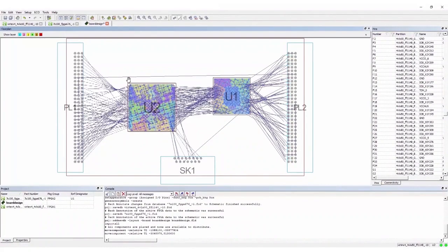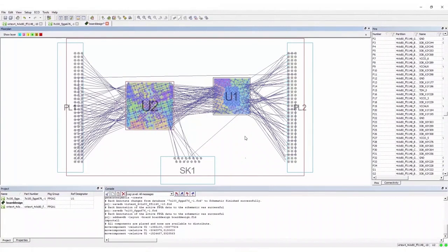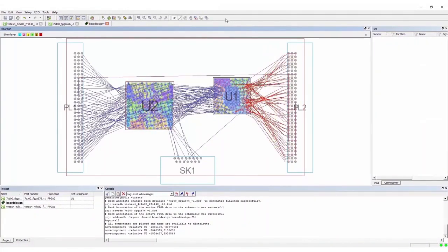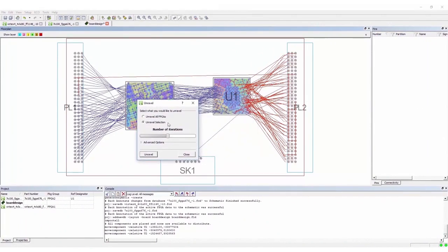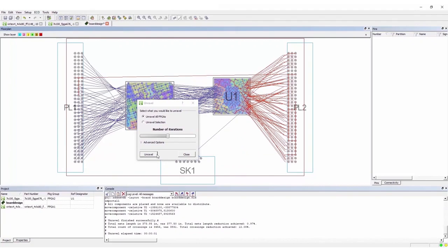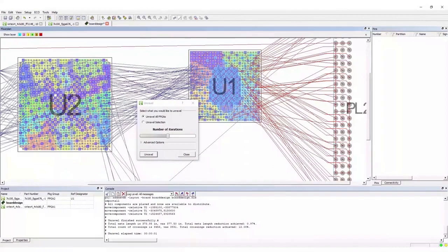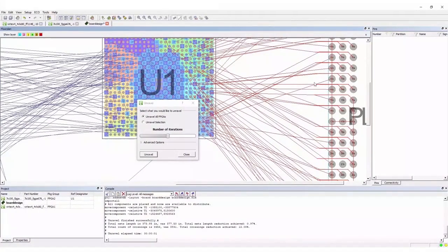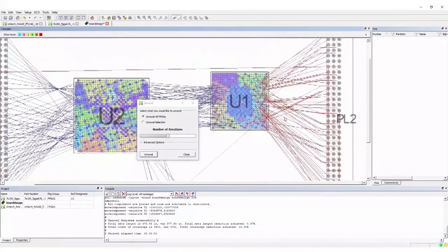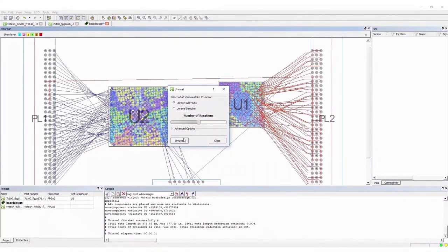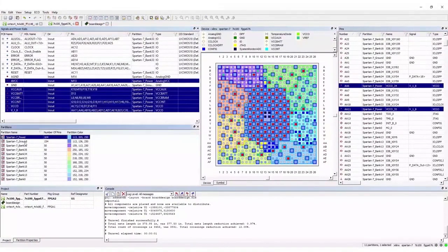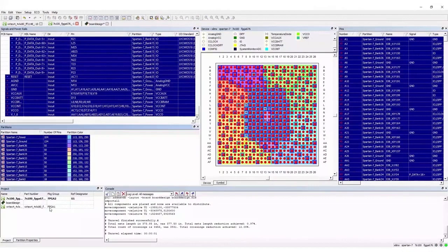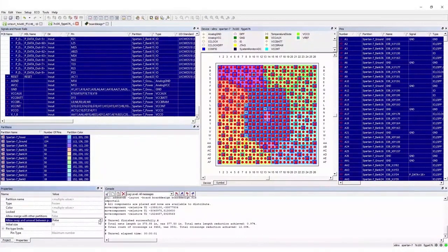You can then start the interesting job of unraveling the selected netlines by swapping pins on the FPGA. The goal is to minimize the net crossovers, leading to shorter net length and fewer vias. Notice that the partially routed nets shown earlier do appear in the floor plan view. Okay, so the result is okay but not great. So let's go back to the Iopt database and allow more swaps, for example, between partitions for both FPGAs.